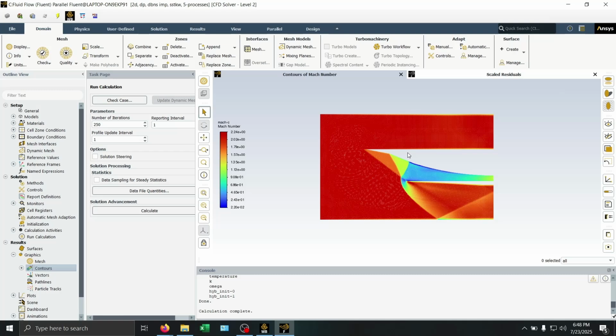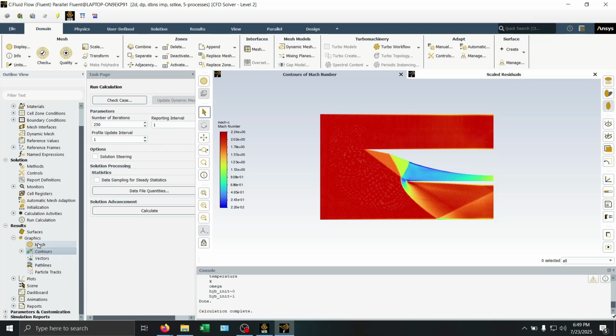And then it should be 1.3 after the second, which again looks correct, right in that yellow here, just below 1.35. And then after the shock it goes subsonic around this range here. All right, close to that. Calculated value was 0.786. So you repeat that for all the contours.